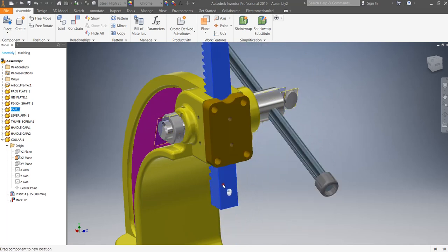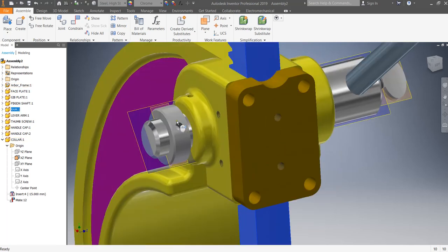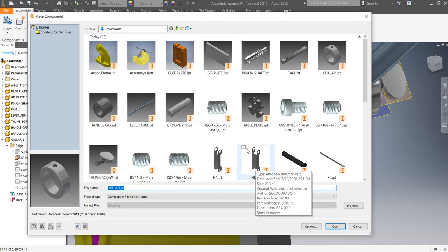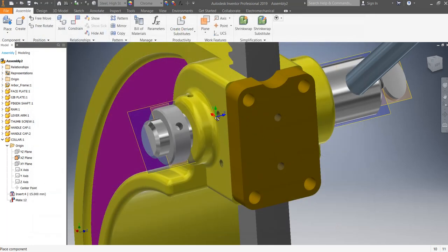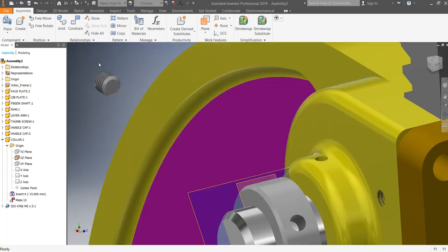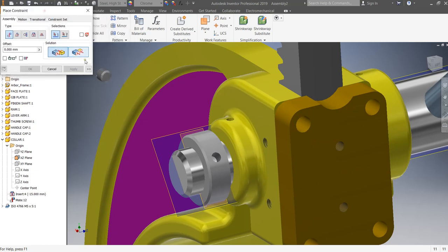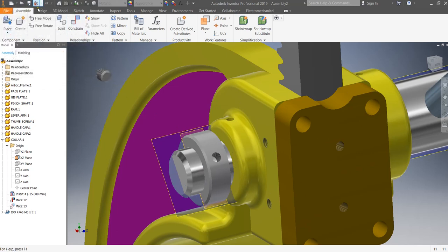Now for the collar, the last thing here also, we have to place or bring one of the bolts. So I know that this bolt is this one. Let me bring it here. Again, same story, guys. We can use insert or axis to axis, tangent. I think better axis to axis and tangent. So mate axis to axis like this. Apply. It's opposite. Cancel. Undo.